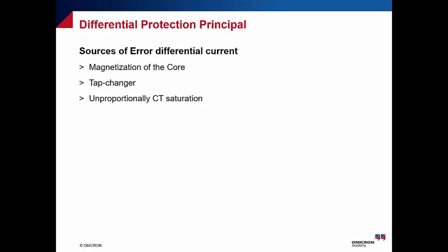Let's talk about one of the important points: why we need to apply different slopes in the power transformer differential protection. Why it is different, sometimes 3 slopes, sometimes 2 slopes, based on the relay manufacturer. Why do we need it? Why is it not like a definite time overcurrent, for example, only a single point setting of the current, if it is exceeded, it should trip, and that's it. It's not possible because of many reasons. Let's discuss some of them.